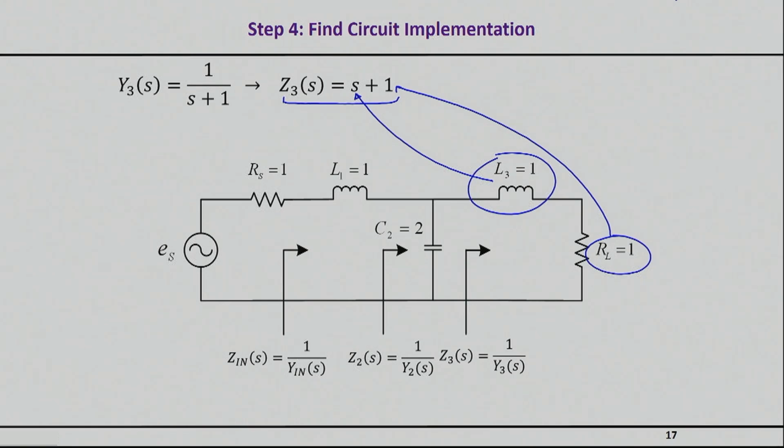So I have now successfully started from a required impedance of Z input as a function of s, and I have synthesized a network that, at least in the normalized domain, where all impedances for source and load are equal to 1 and my omega is equal to 1, satisfies all the requirements that I want. So in principle, you can do this for whatever Z input you have.